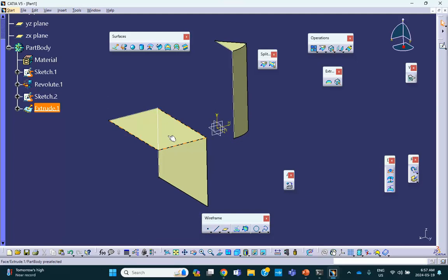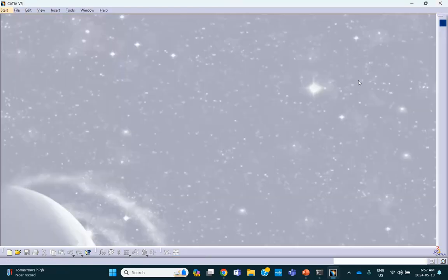Here, it's already joined. Look, when I selected, the whole thing is selected. If I had drawn a line, extruded it, another vertical line, extruded it, then you get two extrudes. So when you select one, both of them are obviously not selected. Okay. All right. So let me get rid of this, and we're going to do our first shell problem.